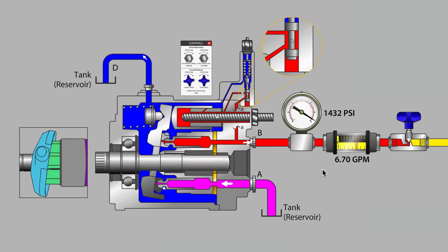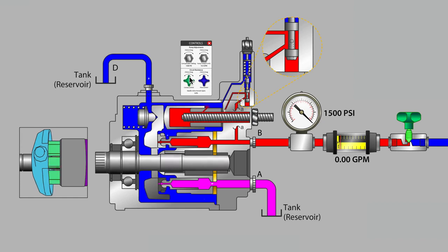At high pressures, a certain percentage of our flow is on the case drain line, especially once the pump is in the pressure compensate mode. Here, let me just restrict that needle valve to the maximum. The pump has gone off stroke. It's still testing to see if there is a flow path present. And of course, our needle valve is closed. The only flow path present is the internal leakage of clearances inside the pump. So the pump only goes back on stroke a very small amount of degrees. And at this moment, our case drain line will be at the maximum possible flow.